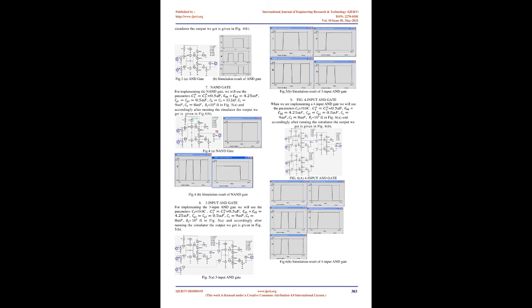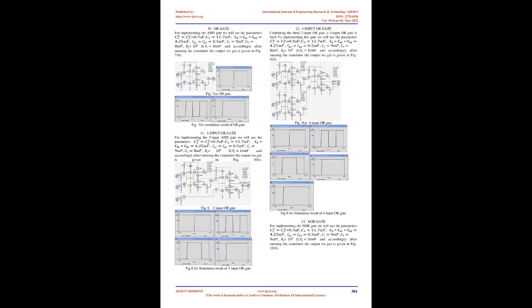An unate function is a Boolean function represented by a formula such that each variable appears either in the positive or in the negative form throughout the formula. As the equations 12, 16, 17, 18, 19, 20, and 21 have their variables either positive or negative for particular cases, they are unate functions. Threshold logic equation for AND gate: F(A,B) equals A.B.